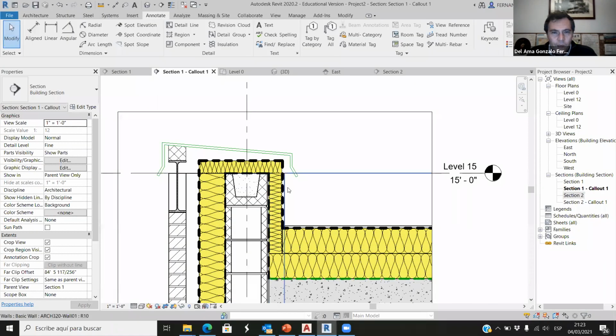It doesn't do any harm, and I think it's good to protect this, because this corner is a weakness in this roof. So the water can end up breaking this waterproof layer. So if we double the waterproof layer, it will always work well.